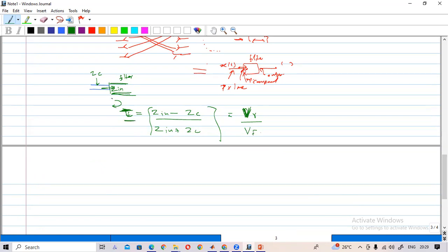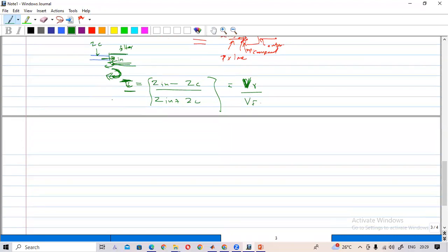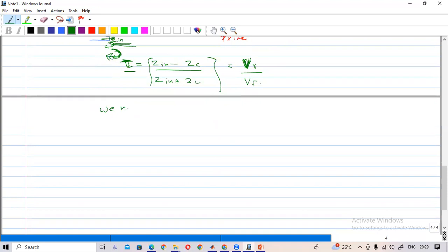So that means some power will be reflected. So that is a problem. That means the wastage of the signal. If the signal is reflecting, that means some signal power will be lost. So that is not good for communication. So what we need to do is we need to minimize this reflection. To minimize this reflection, we need impedance matching.